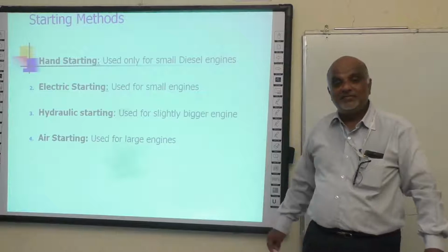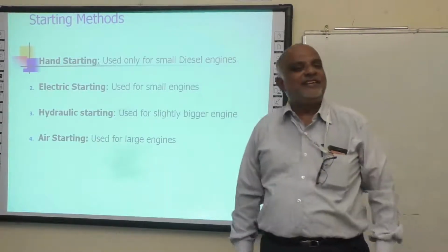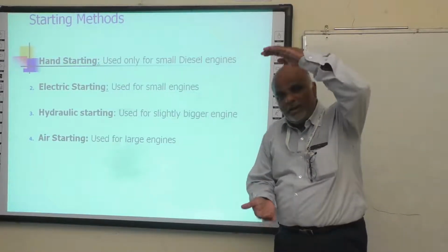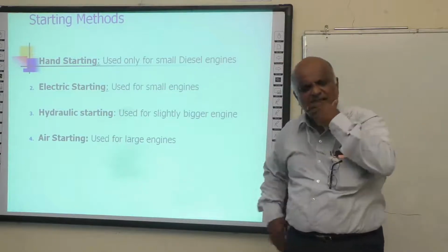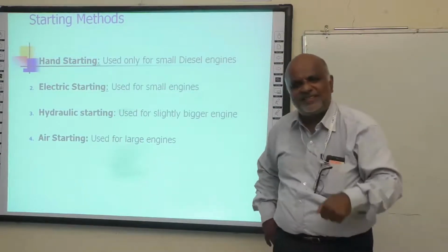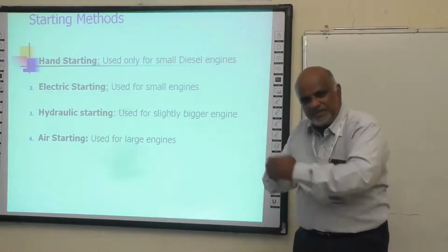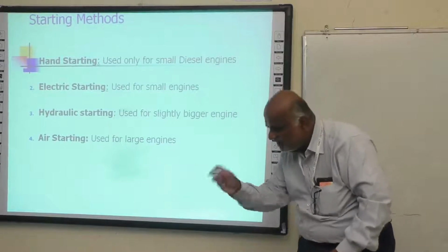This hydraulic starting system is mainly used for emergency generators, which are kept in the aft of the deck, where the oil is kept under pressure. Now, you may ask, sir, hydraulic oil, how does it start? I will explain. A hydraulic pump is there to pump the oil under pressure. You keep it in a pressure cylinder and you open a valve.